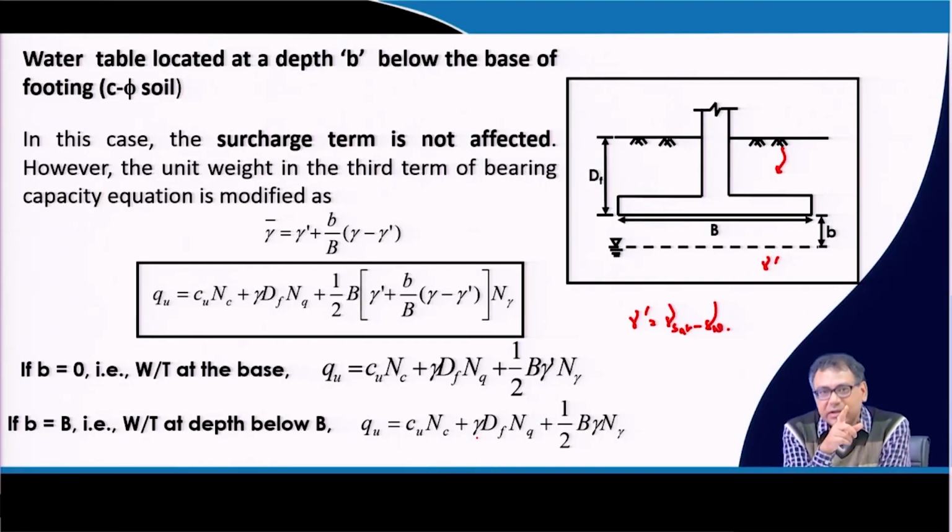If the position of the water table is beyond the width of the foundation from the base, then there is no need to consider the water table effect.